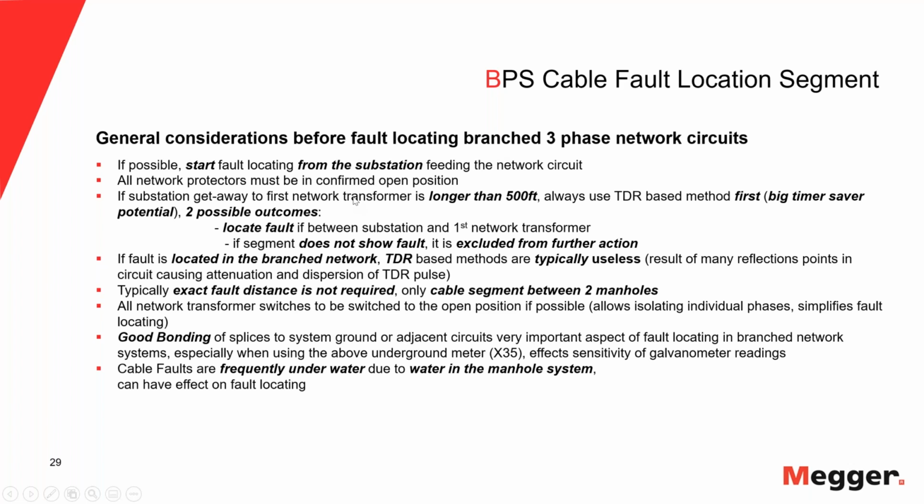Then I have to look at the section going out from the substation. I normally have what we call a substation getaway, and that can be a cable that could run maybe a couple hundred feet, but could also be maybe 1,000, 2,000 feet to the first, let's say, either branch point or to the first network transformer.